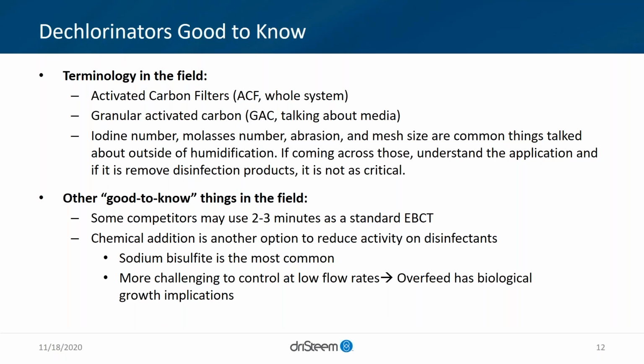Where the dechlorinator really has an advantage is it's essentially a dumb device. You send water through it, it treats it, you send it out. Obviously, all things considered, you need to make sure it's still active, and that's on the maintenance end, and also designed correctly on the front end. But that's really the biggest advantage of trying to do carbon over chemical, not to mention the consumable rate at which chemistry is consumed.